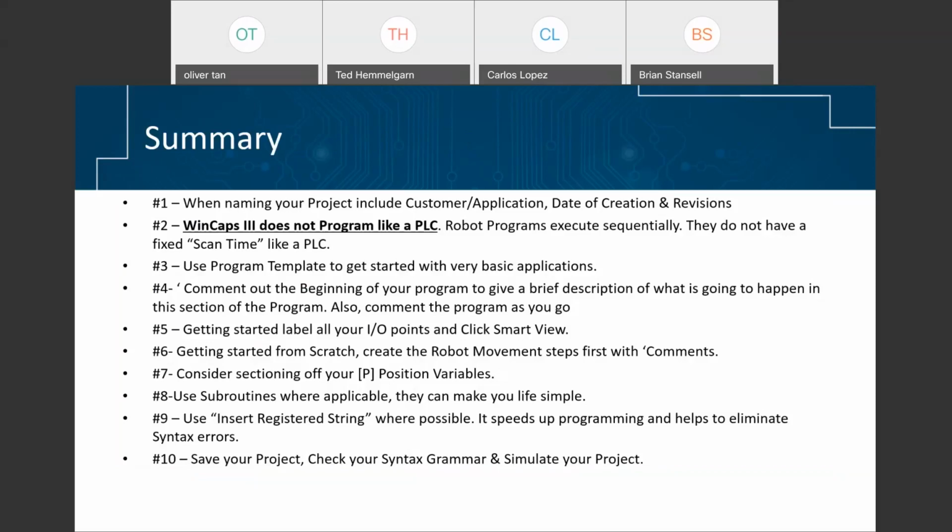So let's just quickly review. Number one, when you're naming your project, include the customer, the application, date of creation, and most importantly, the revision. Number two, WINCAPS 3 does not program like a PLC. They execute sequentially. There is no fixed scan time like a PLC. Number three, I really encourage you to use a program template if you're going to do a palletizing or a simple pick and place, or if you want to incorporate some vision in your application. It's right there, very easy to do, under 3 minutes, and you've got a very basic program.